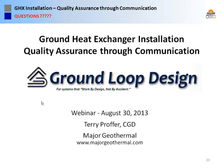A lot of times, what I'll do is ask for the raw data set if I'm the designer or if I'm doing peer review, and I'll put that raw data into my own spreadsheets to do a reality check, because if I've got any question on that power input, I need to know. Beyond that, it's really important before you do the TC test to make sure everyone's got a clean power supply.